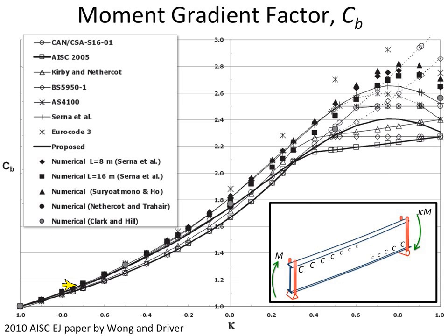And you can see that for uniform bending, everyone's sort of agreeing. But when we get to a significant amount of non-uniform bending over on the right here, there's this kappa factor, which is sort of indicating how much. So when kappa, say, is +1, the moments are in the same direction, and you've got this sort of bending. But kappa could be 0.5 or whatever.